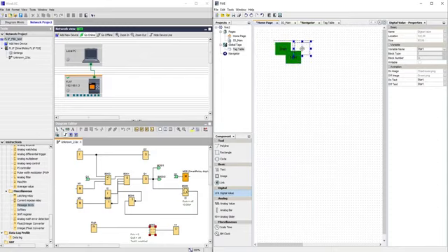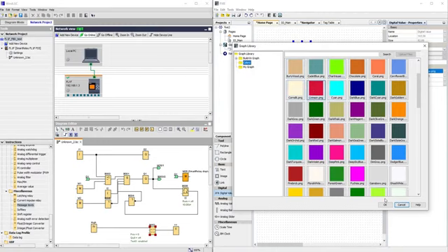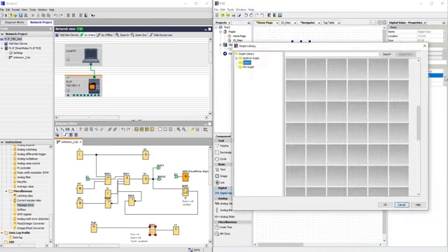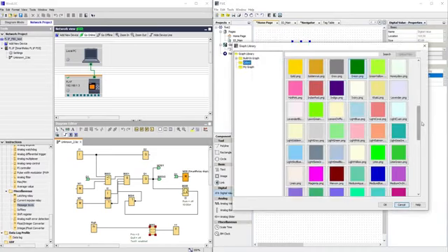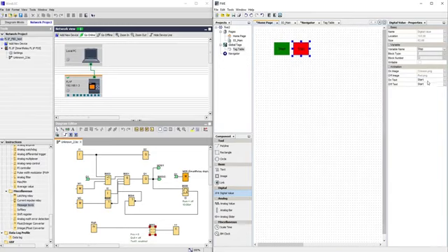Copy, paste. So here I should mention this as stop. Colors I'll change here to maybe this red for font and dark red for off. The text should be stop. So as you have also noticed, when I changed the variable to the global variable stop, automatically the block name, block type and block number have changed.